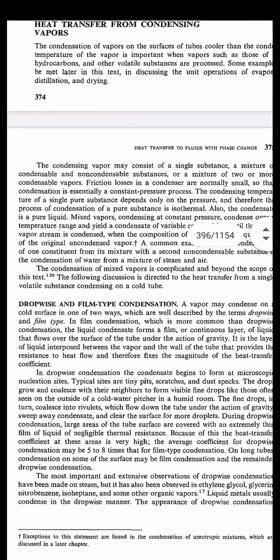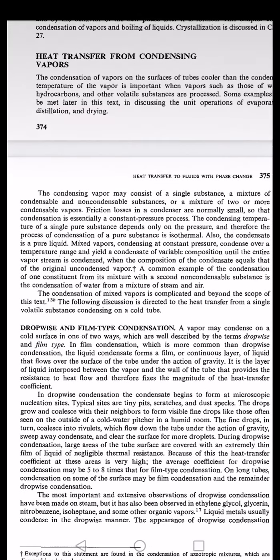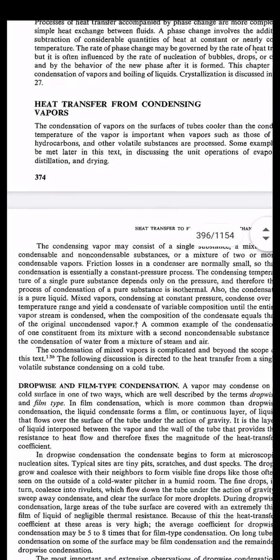So basically, in our last chapter, we have seen that tubes are generally made up of stainless steel, which has a glossy chromium layer. Such a glossy surface always favors film condensation. To enforce dropwise condensation, it may be tried by using various sticky materials like wax, or oleic acid or some compound.